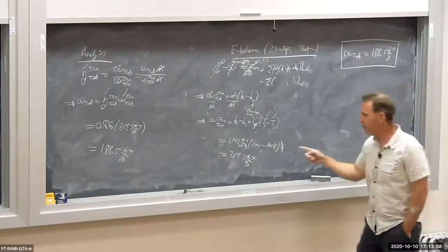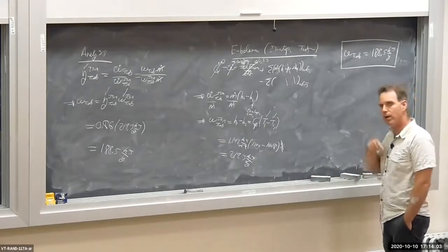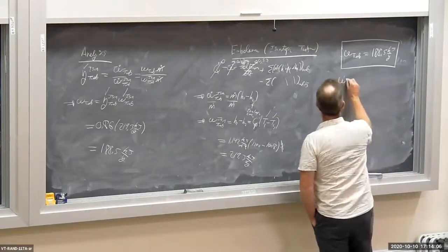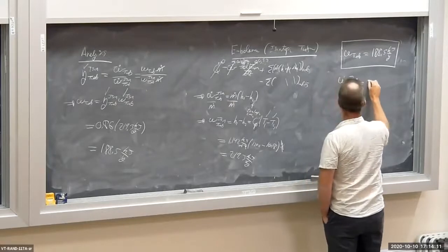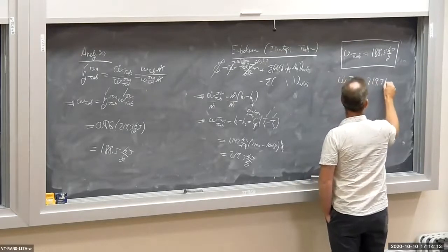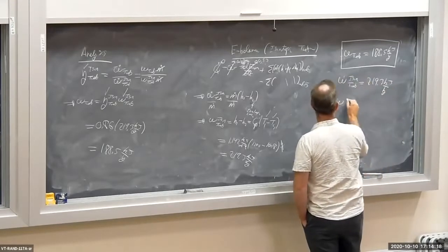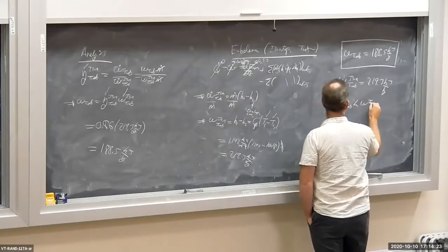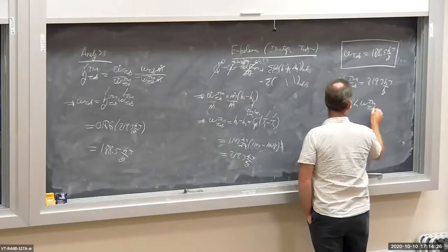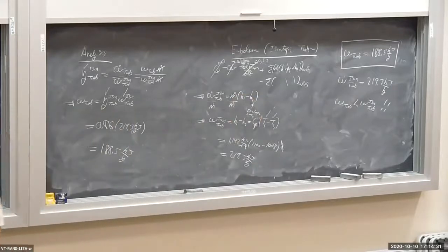Note, the reversible device, the one that produces the maximum possible work between the same pressure limits, W isentropic turbine, is 219.3 kilojoules per kilogram. So W turbine is less than the isentropic turbine work. The real turbine produces less power than the isentropic turbine.